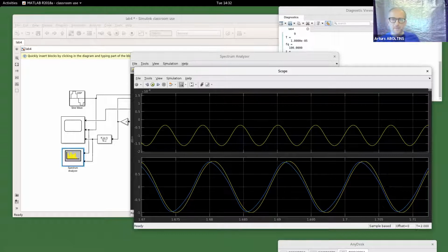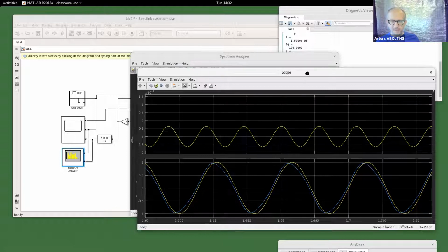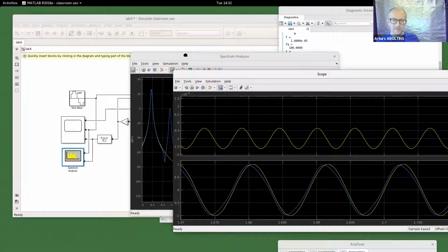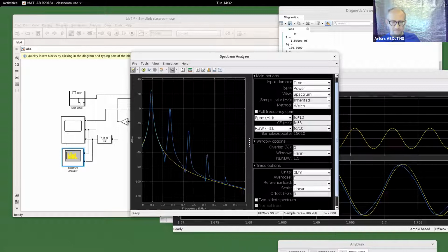And this is a big problem, because if you now feed this signal into the receiver, for example, for the down conversion, all these harmonics will create byproducts. And those byproducts will get mixed with this useful signal, and will decrease the sensitivity of the receiver and create some other problems.